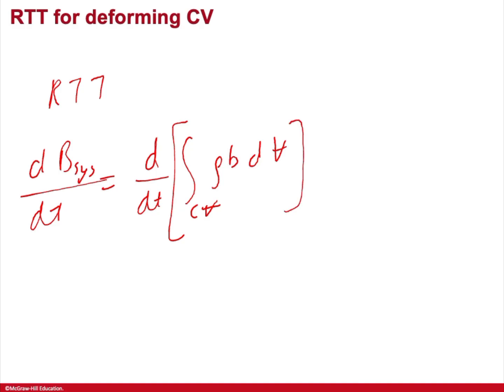So the key thing you have to be mindful of is that you cannot bring this time derivative inside anymore, because your control volume is not fixed, it is constantly changing, the shape is changing.